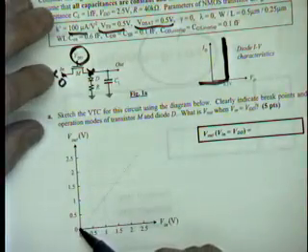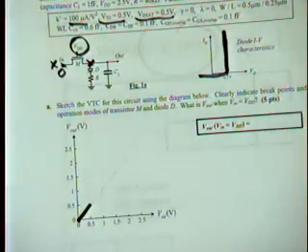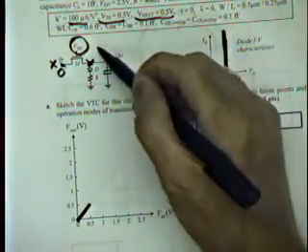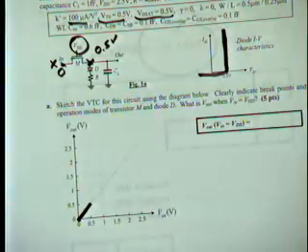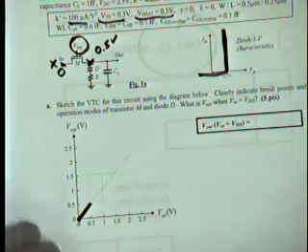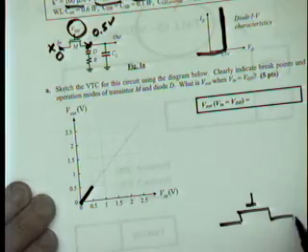So we keep on raising V in. V out is just going to be equal to V in initially. They're just going to follow each other. Then, suddenly this becomes equal to 0.5 volts. Now we have a different story, because now suddenly this diode is going to turn on. The diode is basically active, and we're going to have now an equivalent network that looks something like this.